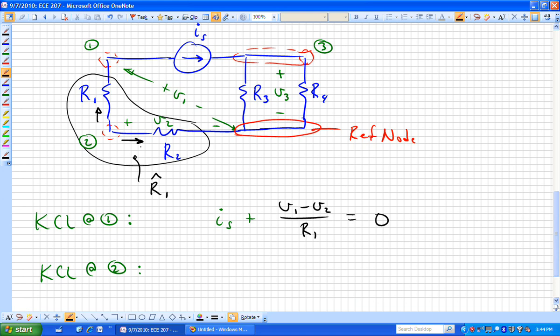I'm trying to understand where the question is coming from. There's a question with why I label my node voltages in the manner that I did, and V3 seems obvious. Don't confuse the polarity of my node voltages with the direction of the current source.